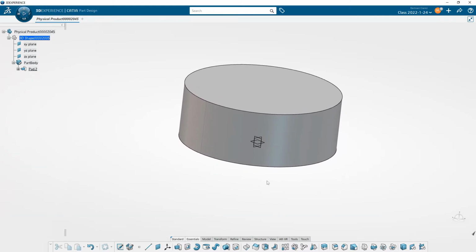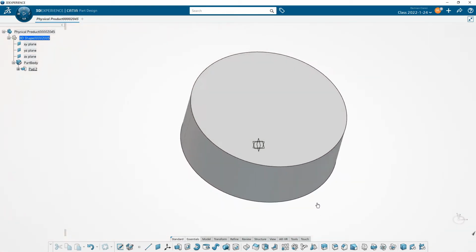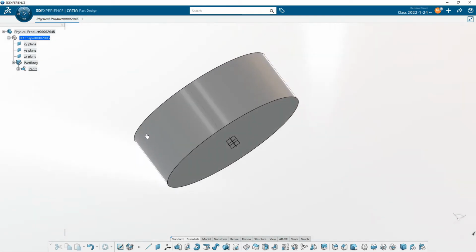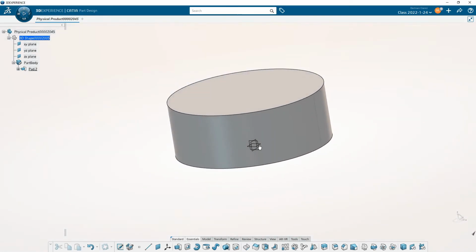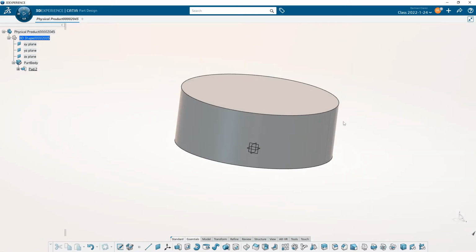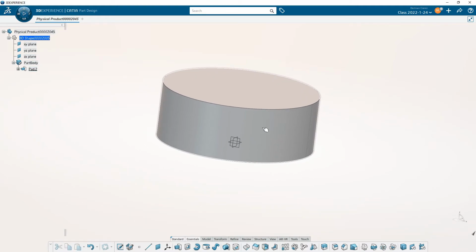And then if I want to rotate, I hold down 2 and then 3. That's kind of the order that I do this in. Push 2 first and then 3 and keep holding them. And now you can rotate this around. It's going to feel awkward for a little bit, but you will get used to it. Let go, and then I want to tell you about zoom. The way, again, that I feel that they put this together is actually fairly ingenious for a workflow. It's not so good for beginners because, again, it kind of hurts a little bit, but like I said, you'll get used to it. If I want to zoom, just like rotate, I do 2 and 3.